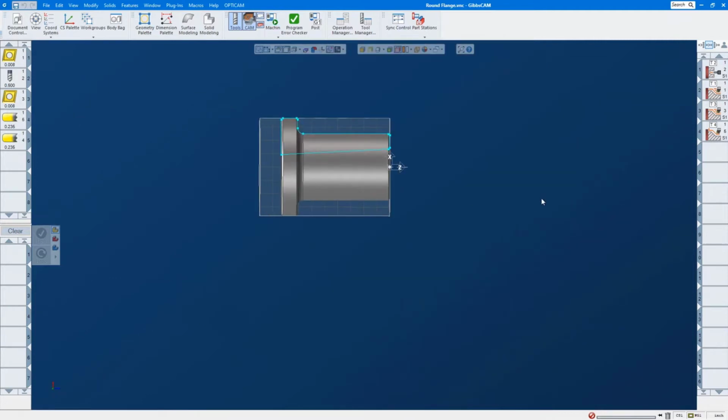I will warn you, however, in my opinion, and this is only my opinion, whenever you start something, make sure you're using the configuration that you want to use. Because some of these things aren't going to work on a 24 milling spindle, or I should say it shouldn't go backwards. If you have a turret that has milling capabilities and you go to a turret that doesn't, they're going to be all X'd out because it doesn't apply.